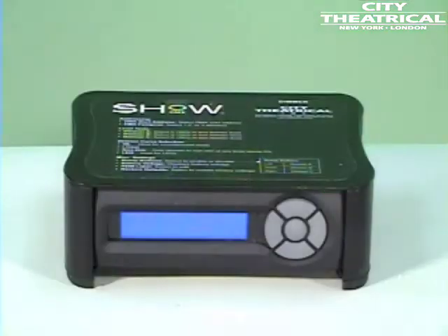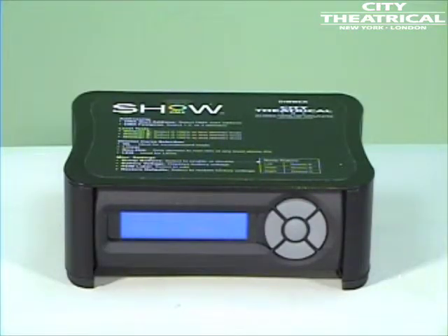Now let's look at a SHoW DMX dimmer. Transmitters and receivers act together as an RDM proxy system, providing a bidirectional half-duplex RDM link between the controller and any RDM device being controlled via the SHoW DMX system. In this case, we're looking at a City Theatrical 3-channel low-voltage dimmer. The same type you might use with a battery and a receiver to run an LED or low-voltage load, but it could be any RDM-enabled device.